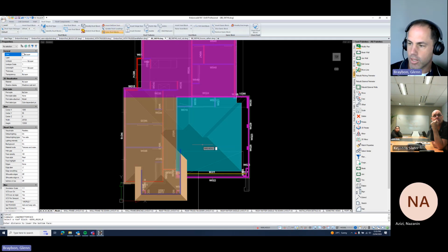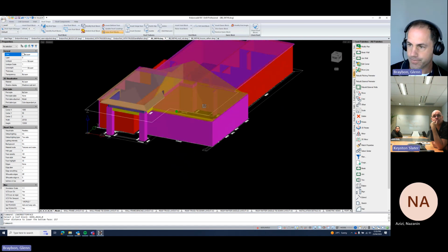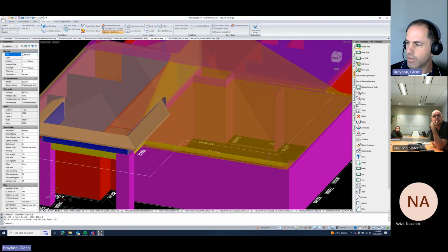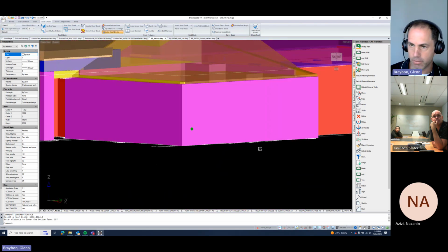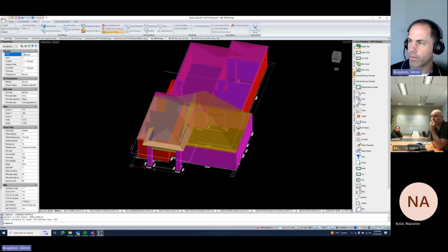Select the roof block. Is it 257? Yeah, 257. Cool. So we'll just do that, and we can see that we have lowered that face. Close. Maybe my detailing is a bit wrong with some wall heights, but we've got something similar probably to what we require.